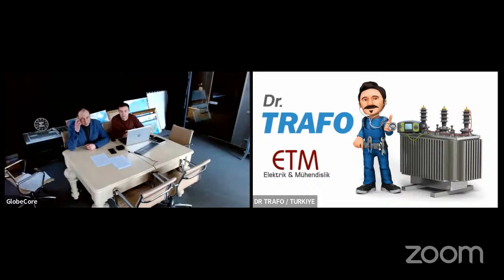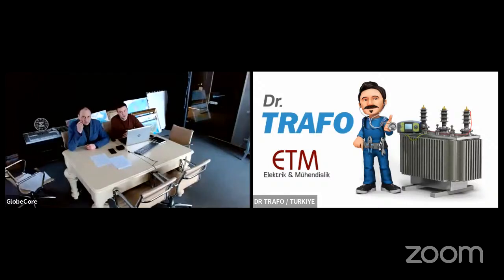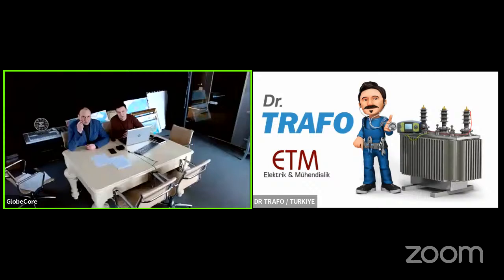I have a second question, so I don't know if you would like to answer this, and then I will add the second one. Well, Mr. Samuel, I can send you by email the brands of inhibitors that we can recommend to buy. Okay. But usually you use this after regeneration, if I'm correct. Yeah, actually, inhibitor injection is the last stage of regeneration process. So you put the inhibitor just before you put the oil into the transformer.